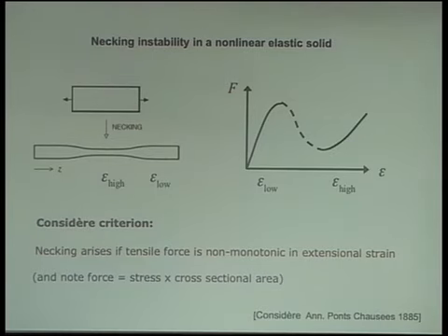What we're thinking about here is a very long-standing problem in mechanics. It's thinking about taking what's initially a cylindrical thread, seen here from the side, and attempting steadily to draw it out in length. And we have something called a Hencky strain, so let's think about what that means. If you have a constant rate of Hencky strain, at any point in time it's deforming at a rate that's proportional to its length, so that corresponds to exponentially separating ends of the sample as a function of time. And what we usually find is that we can't deform these threads in a way that stays homogeneous, but they tend to form necks in the middle of the sample and may even eventually snap.